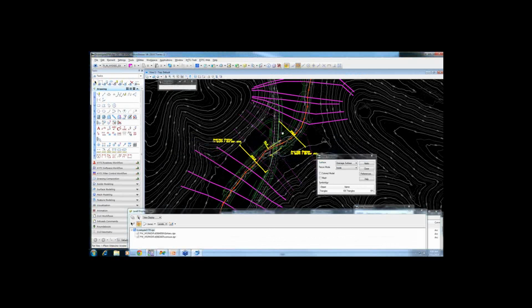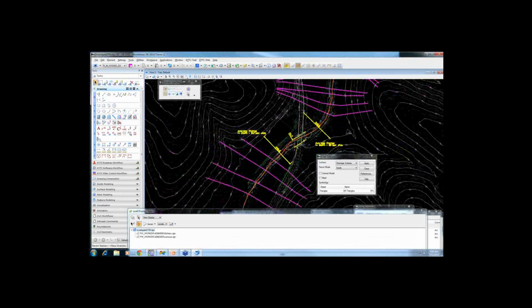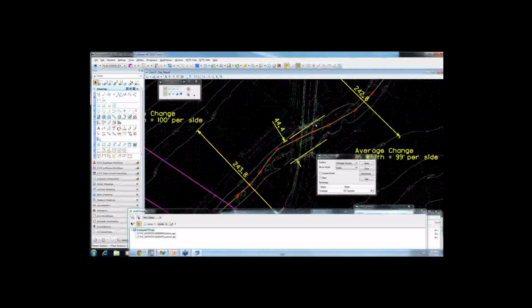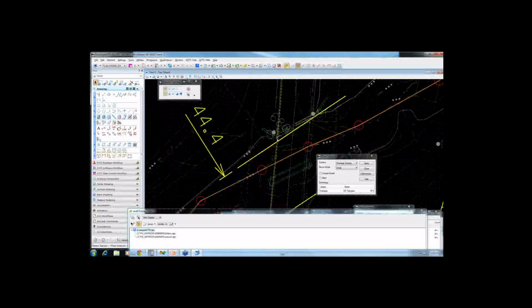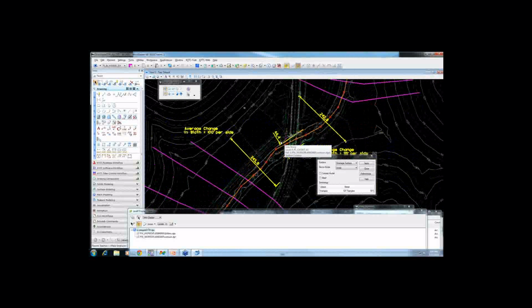figured that. What I did is I measured my bridge opening, and I measured it with the direction of flow. I said flow's roughly going this way, so I'm going to lose a little bit of my bridge opening due to skew. But I measured about 44 feet. And then I went upstream, and this can take several iterations. If you don't guess the right spot, you might have to measure here and then do the math and figure, well, this section should actually be at a different location.